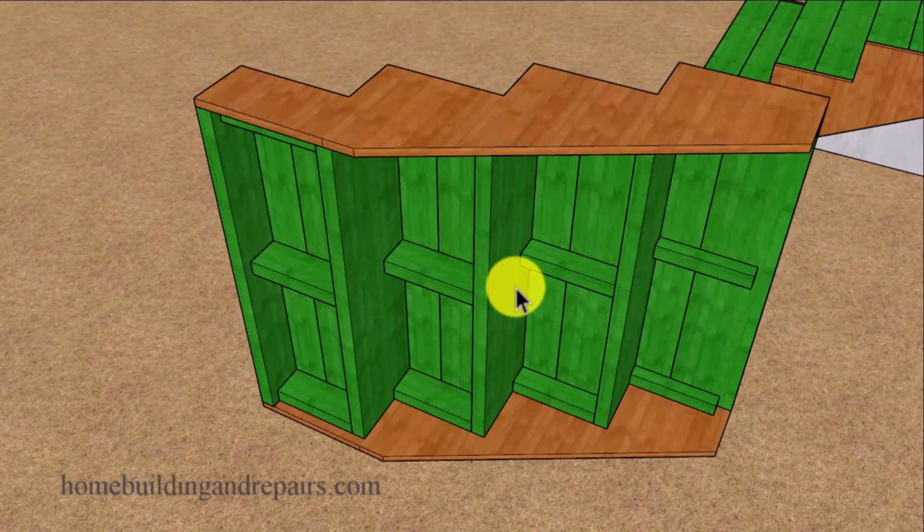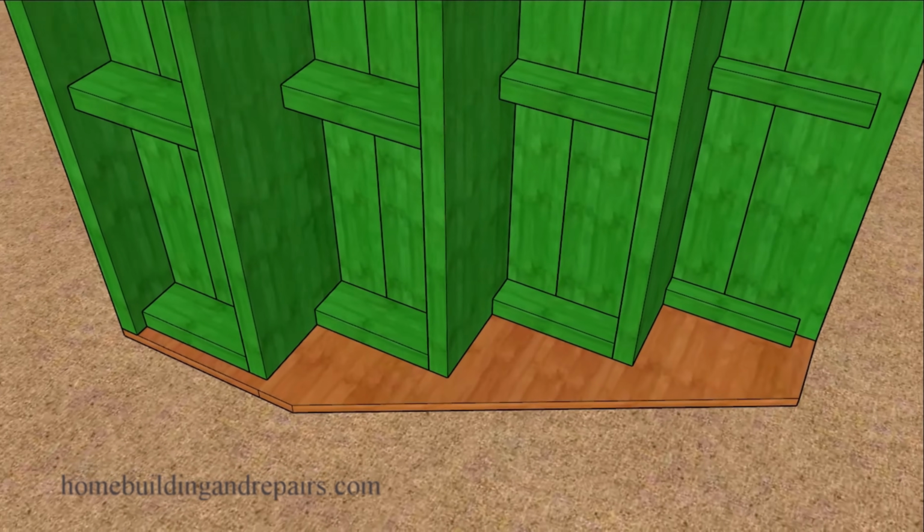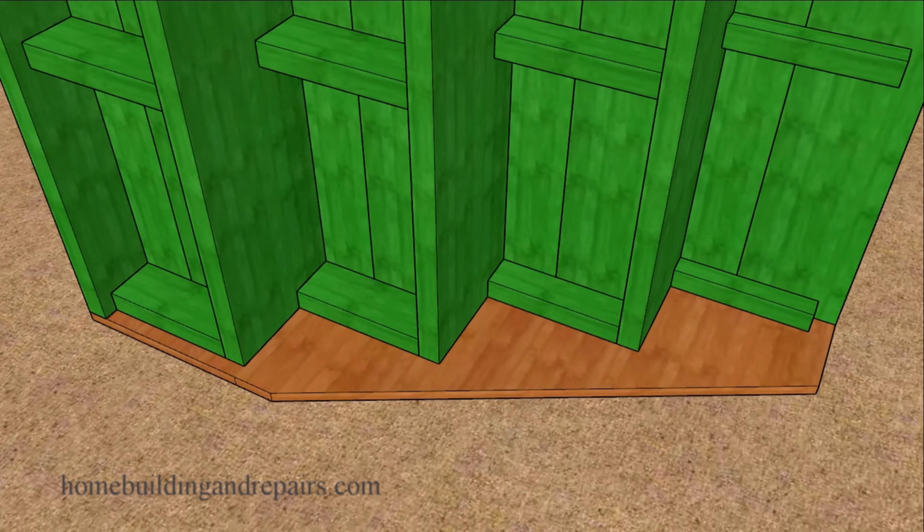And make sure that you nail or screw everything together, including the back of this board to your boards here. And if you are going to build it and then install it over the stairway, it wouldn't be a bad idea to check it in sections. So maybe build these 2 sections together and then set them over the existing stairway to see if everything's working. And it might not be a bad idea to use screws on the sides. Maybe only put a couple of screws in on the sides and then set everything in place to make sure that it is going to work and you don't need to make additional modifications.